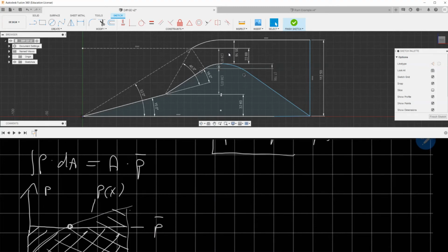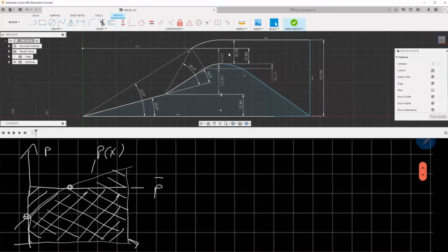Also take a look, because I'll have to put another section in the report for this calculation, it's not easy. Area average values: the area average value is actually the same thing I showed you here. ANSYS calculates this average and gives it to you as the output when you generate in the report some area average, for example, area average pressure or area average velocity.